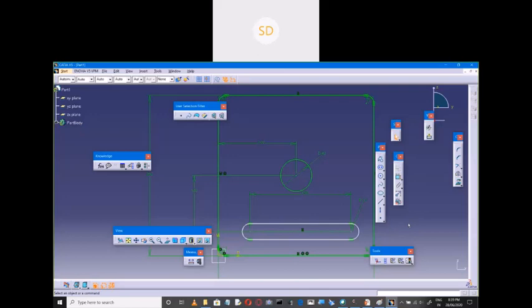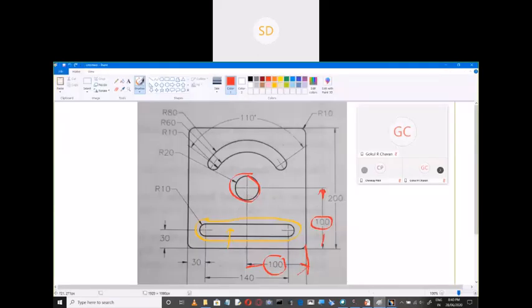So next you need to draw the arc shape hole. Okay? So that is what we call the cylindrical elongated hole. Now I'll click here. I'll go for a cylindrical elongated hole. Okay. So first you need to define the center point. This is the center point. Okay. Next, what is the radius? It has been placed. You just observe.